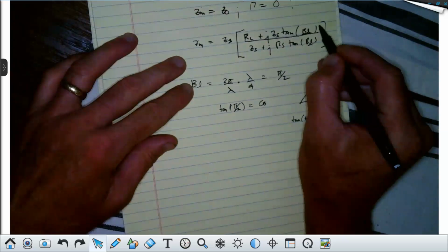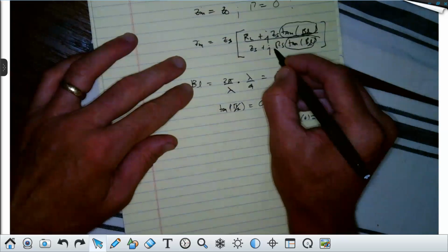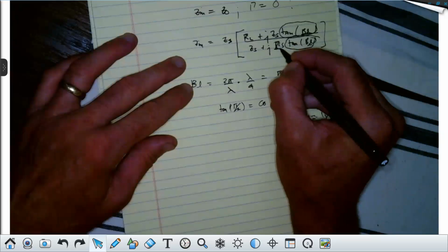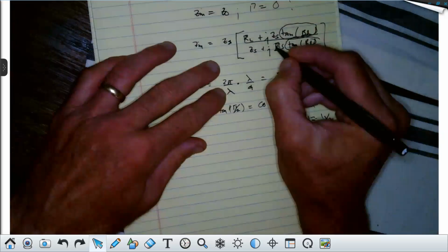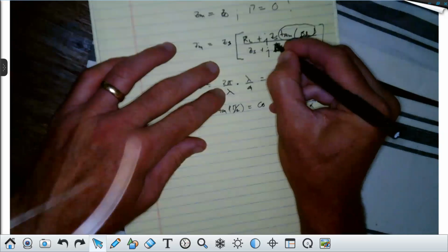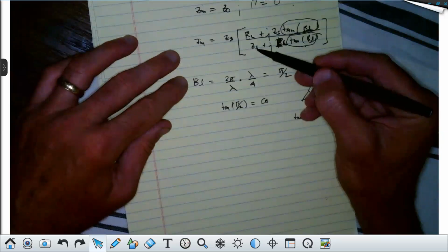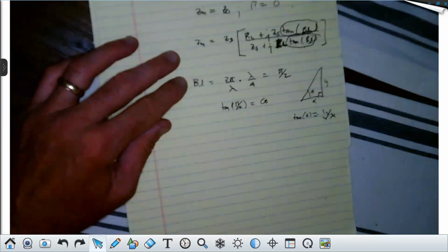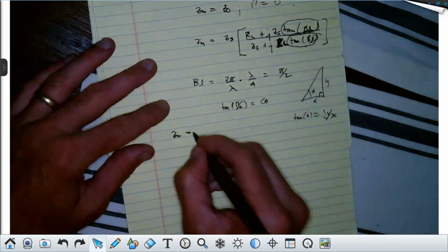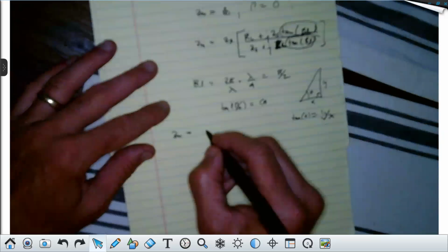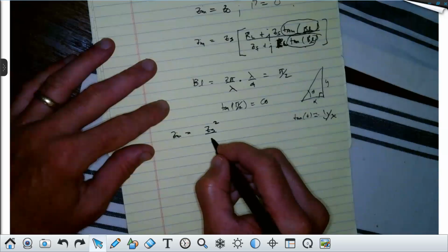This quantity right here is tending to infinity, and this quantity is tending to infinity. That's supposed to be RL, my bad. I don't know why it didn't show up. Now, if these two quantities are becoming enormous, this quantity and this quantity become inconsequential. They're negligibly small. So I can actually say that Zn here, when it's a quarter wavelength long, will be equal to simply Zs squared. The tangents will divide out, divided by the actual load impedance, or RL.